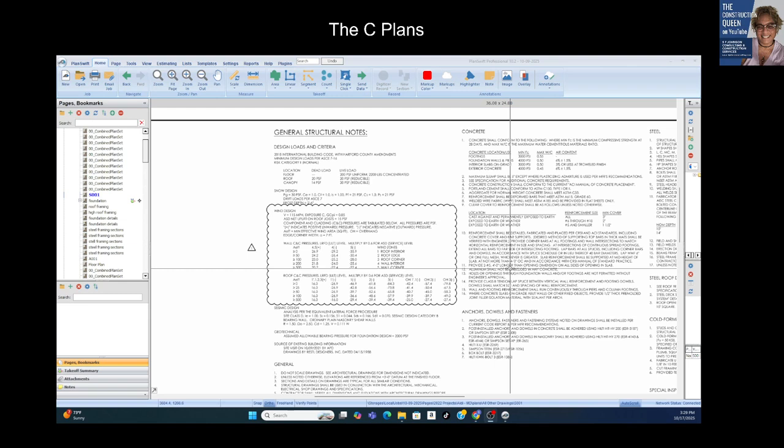So the top of it is the roof. It weighs a certain amount. That's why we have to have headers for windows and doors. Because if we take out a structural wall, which is any exterior wall, we have to size that back up because we have to be able to hold that load of that roof. The thing that was holding it up was a solid wall on concrete. Well, now we have put a window, which is basically compromising that strength by putting that hole there. So we have to strengthen it back up.